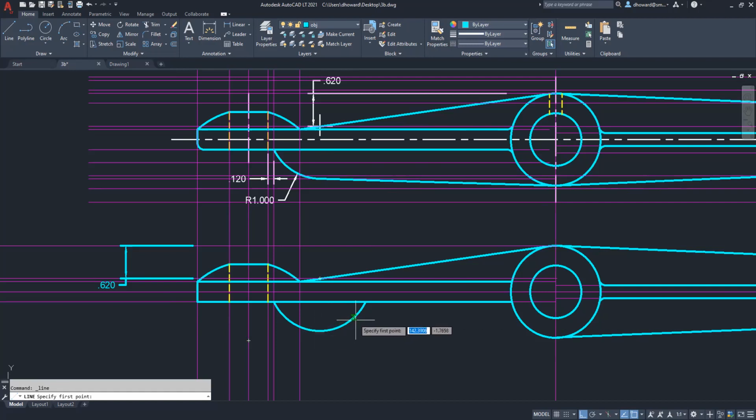So I could just snap it down here, let's say, and then on this side, snap it to tangent. And now I can grab the endpoint and snap it to tangent over here and make sure the tangent snap is lighting up. I think it's pretty much on center. There it is. Tangent line, it's almost exactly on center.